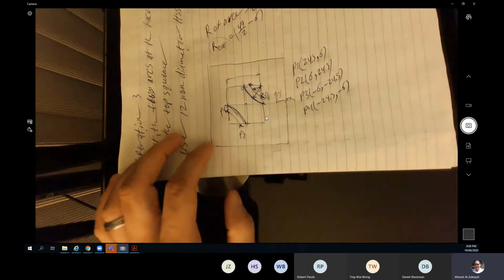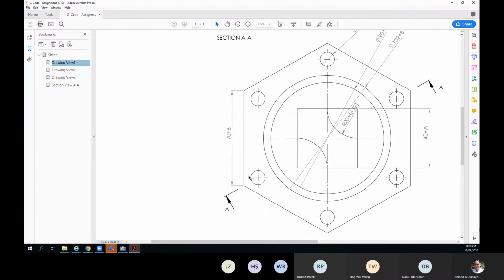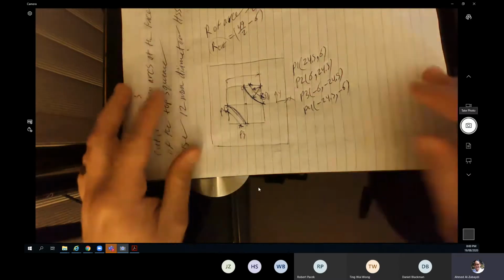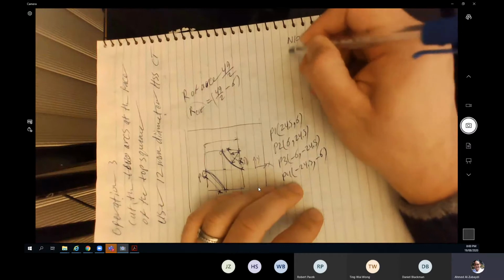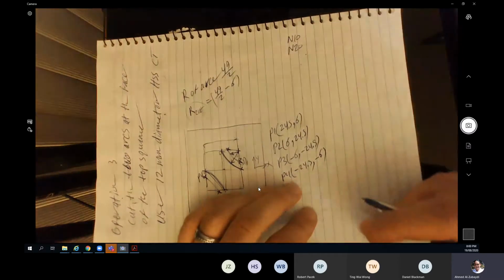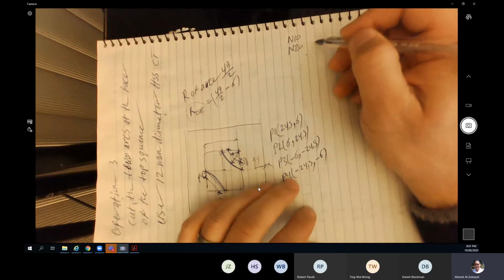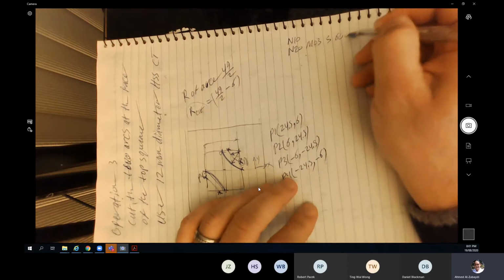The depth of the cut was 3 plus b over 5. So it's going to be almost 3.5. Let's say it's going to be 3.5 if the b is equal to 9. So the code is going to be very simple. Once again, we need to write down the first N10 and N20 from the first line we used for the face milling. But just remember that this will be tool number 2. And then we start the spindle M03 with a spindle speed of 600, for example.